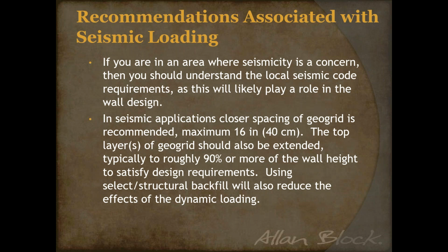One thing that we found is that in seismic applications, geogrid placement is particularly important. The maximum allowed spacing is 16 inches. We have an 8-inch tall block, so 16 inches would be 2 courses. I did mention 2-course spacing is standard for all walls across the industry. Sometimes in a standard application, we do allow 3-course spacing. We never recommend going above that. But if seismic activity is involved, we set the cutoff at 2 courses or 16 inches.